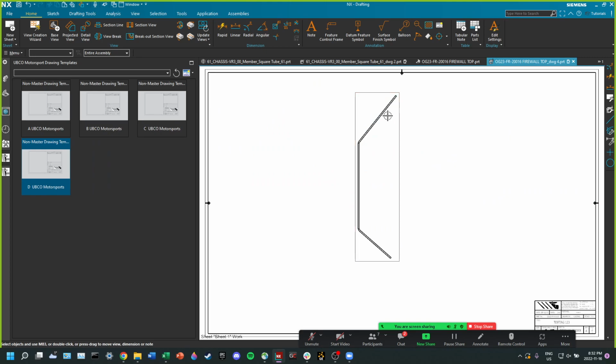For each of our parts, what's important to consider when you're making a drawing is how that part's going to be manufactured. Just because you can put a dimension somewhere doesn't necessarily mean that that's a useful dimension. And this also ties into the modeling practices that we shall be trying to use, in that how we set up our CAD model will affect how we're able to dimension our part, which will affect how we're able to manufacture it.